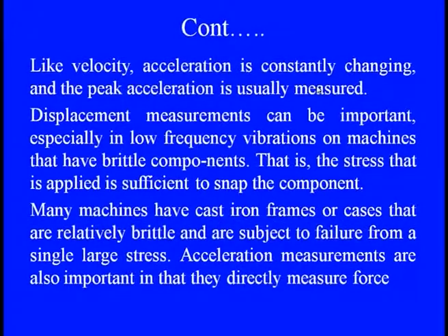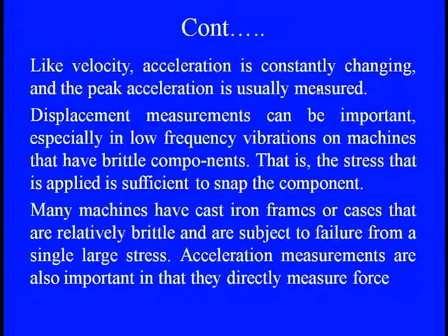And when we are talking about these brittle components, the stress that is applied is sufficient to strain the component, and whatever the variations are, they can be easily measured using any displacement sensor, LVDT or something, or the strain part. So, many machines which have cast iron frames or cases are relatively brittle and are subjected to failure from a single large stress.